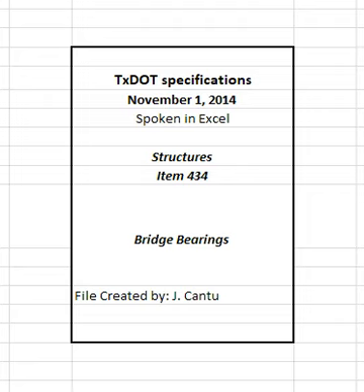Provide a design that uses sole plate geometry or a grout interface to accommodate the longitudinal and transverse aspects of the bridge grade, and does not require the bearing to accommodate this in rotation unless indicated otherwise on the plans. If the bridge element supported by the bearing is cambered for dead load to be applied after the bearing is positioned, the dead load design rotation of the elastomer may be neglected provided the fabricator-developed design has checked the bearing for this temporary condition to ensure no damage occurs and there is no metal-to-metal contact.